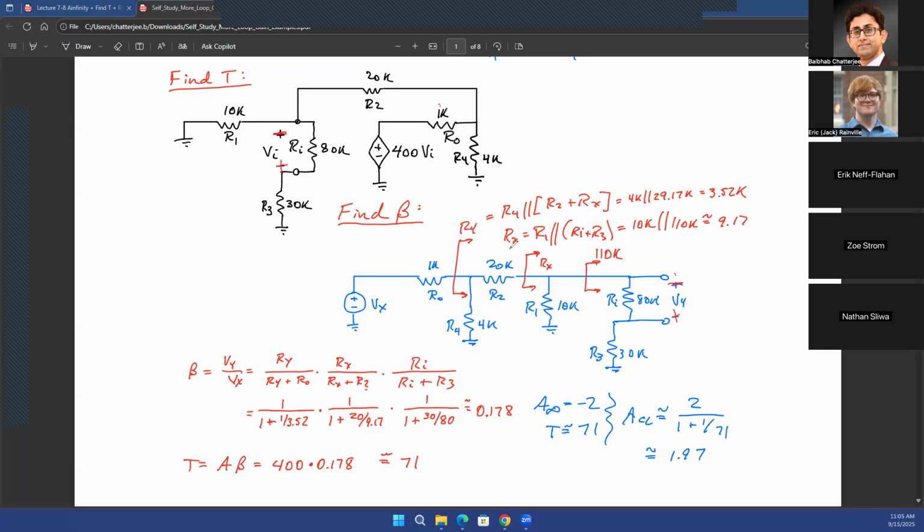All right. So you can find out your Rx as a parallel combination of 10 kilo ohms and 110 kilo ohms, which is very close to your 10 kilo ohms. Now, I leave that up to you, how accurate you want to be. You can be accurate up to 5 decimal digits. You can be accurate up to 1 decimal digit. Everything is fine because your final answer will not change much.